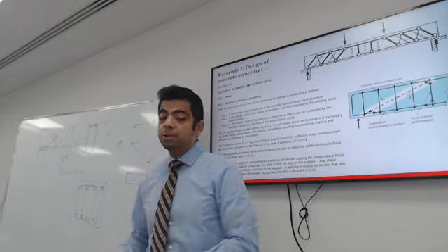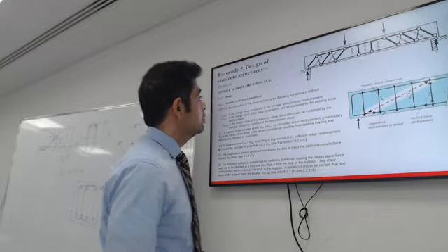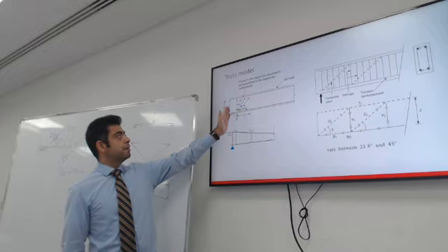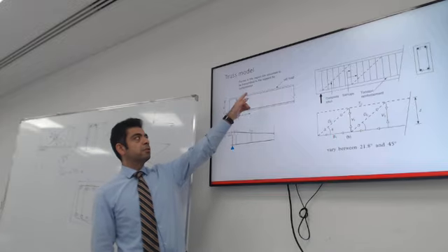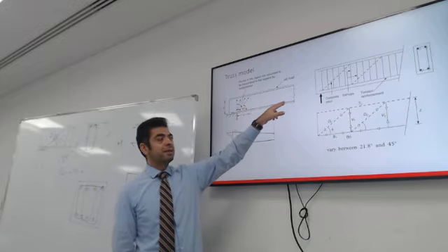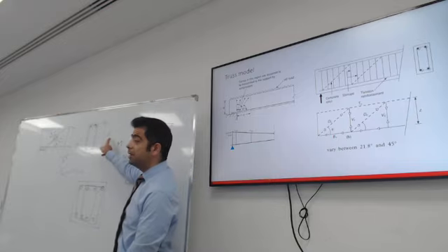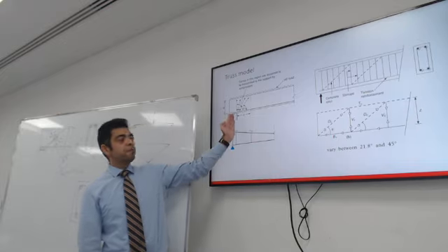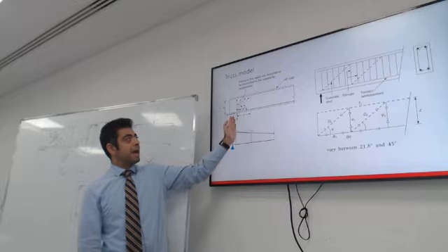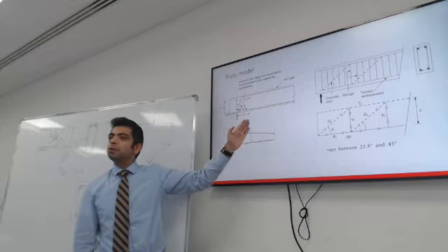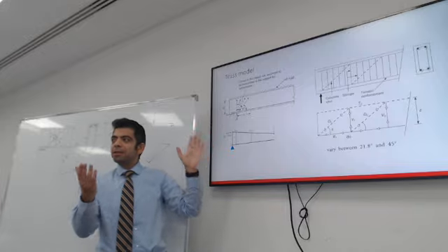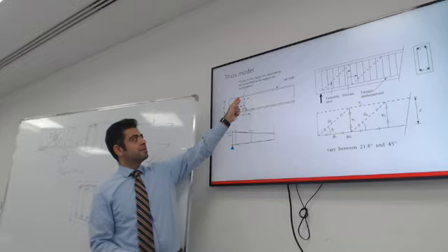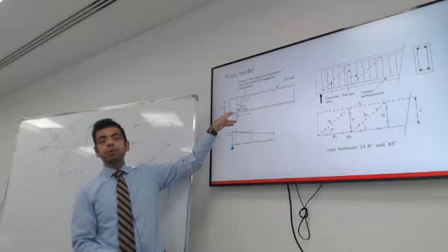Because of this assumption, you will realize something that we can use to our benefit. If the distance between the very top compression fibers to the centroid of steel is D, then from the face of the support at a distance D, we don't need to include shear within this distance in the design, because any load within this distance is going to directly go to the support.